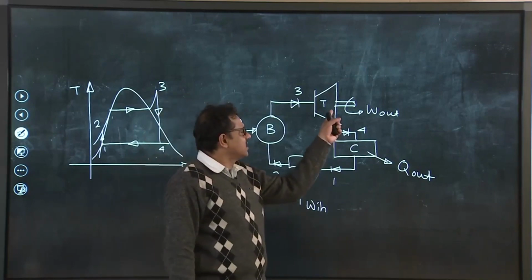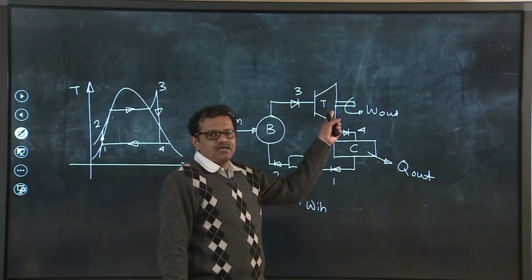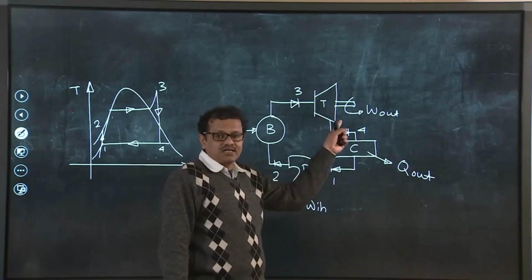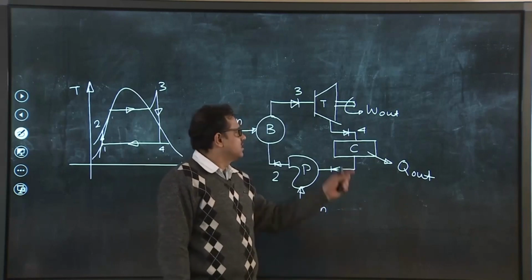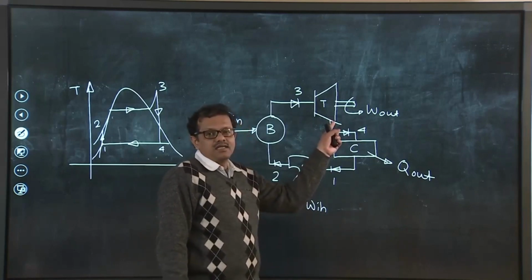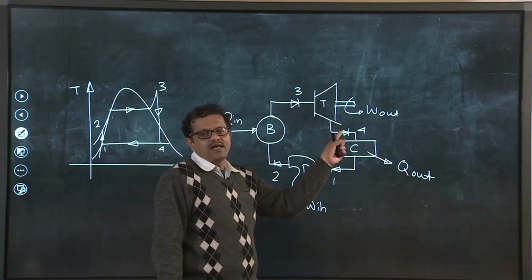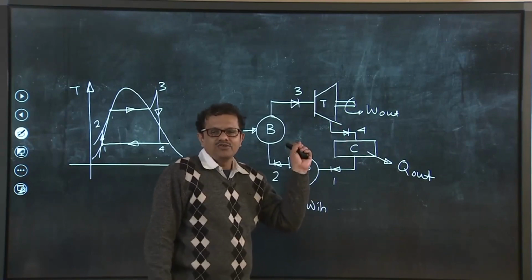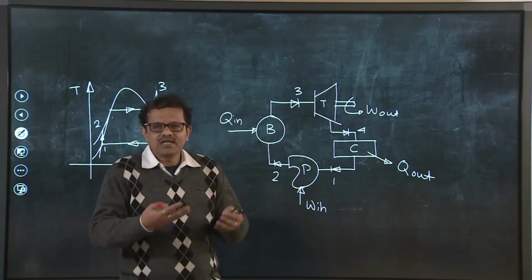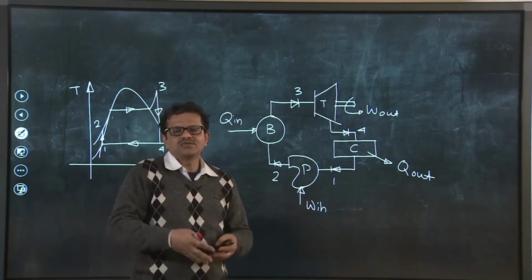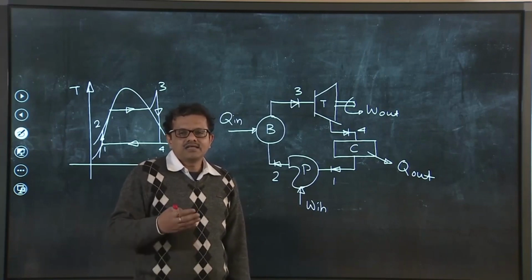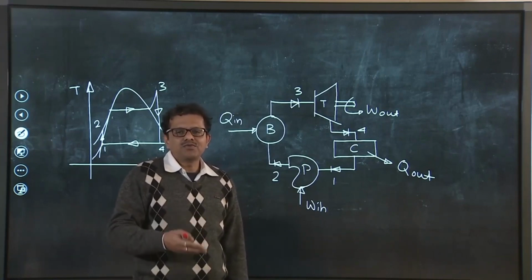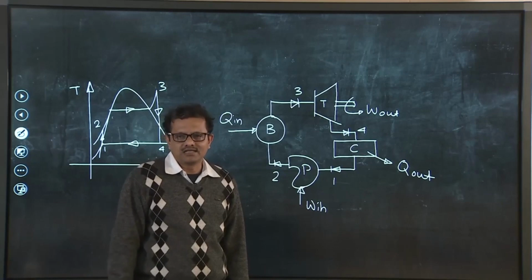We can understand that if we would like to discharge the steam into the ambience, then the steam will be discharged at the atmospheric pressure, and we know that steam will release heat when it is discharged to the ambience, then the saturation temperature corresponding to atmospheric pressure is 100 degree Celsius.